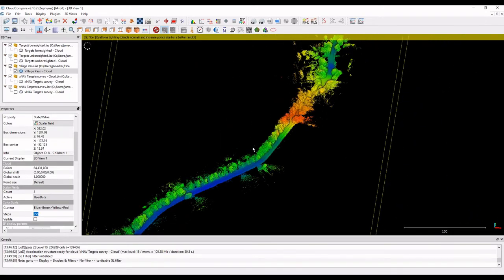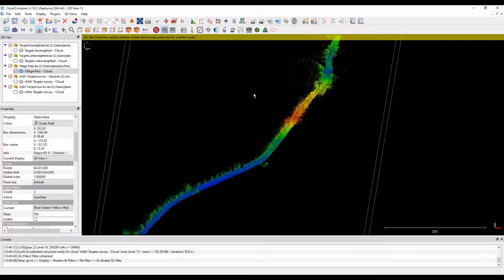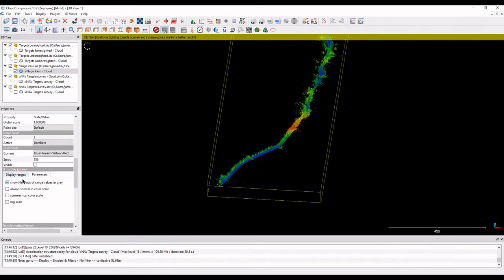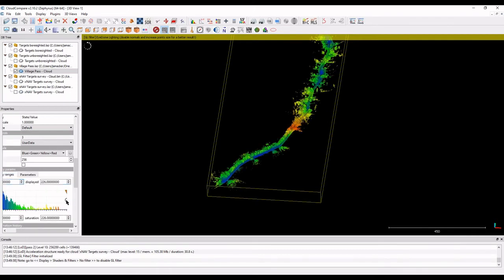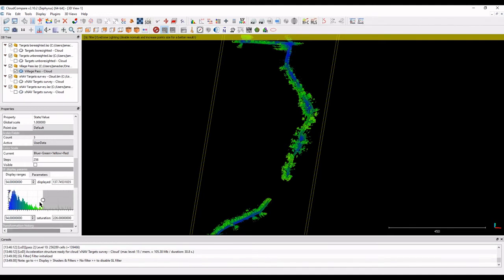Something you can do is choose in Georeferencer to edit out inaccurate points if you wanted to, or you can keep them. You can now edit them out here. So for example, I can simply edit out inaccurate points. So you can see exactly where you might want to resurvey if you wanted to do that, or just ensure that you've got the highest accuracy points and none of the rest of the point cloud is being affected by those.